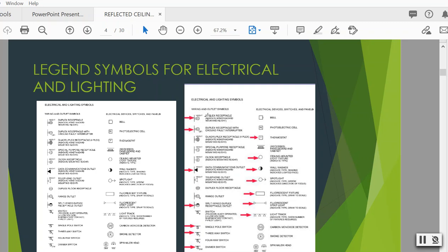Now above this, it says the word height. If you don't have a number there, then that's just your standard outlet. Usually most outlets are about 11 to 12 inches above the floor. But on occasions, you have a countertop outlet. In those occasions, you must put the height that you want that outlet. So if you had a countertop outlet, it would be approximately 48 inches above finished floor. That tells me that that outlet is 48 inches above the floor. It gives the electrician a heads up of where to place that.